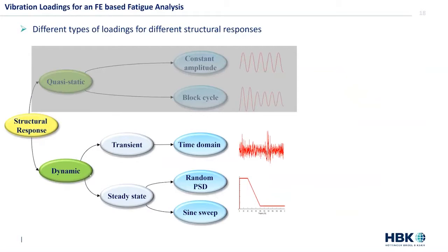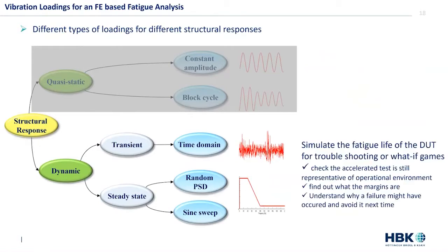And in that case, indeed, you can take time domain excitations or frequency domain excitations. By frequency domain, I mean PSDs, as we saw so far. It could also be sine sweep or sine dwell, etc. So the idea here is eventually to excite your FE model with those signals or spectra and simulate what's going on in terms of fatigue for the device under test.